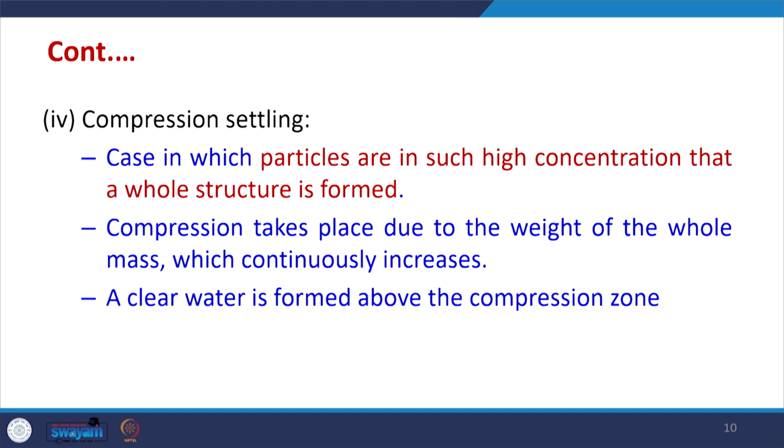Then we have compression settling. In this case, the particles are at such a high concentration that a whole structure is formed, and compression takes place due to the weight of the whole mass, which continuously increases. The clear water is formed above the compression zone. That means the clear water is above and all the settled particles are at the bottom.